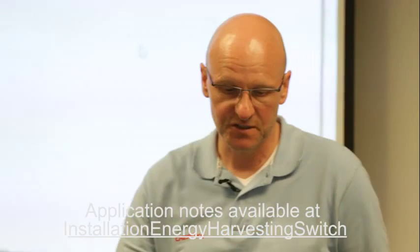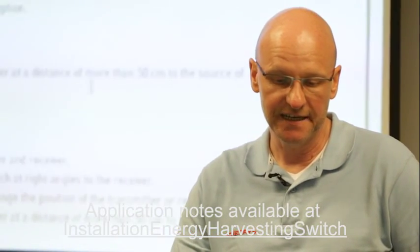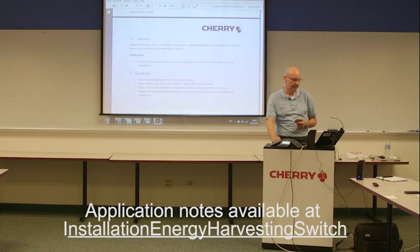Also reflections or interferences can happen inside buildings, as described in this installation guide. Jamming by other electronic devices could be another problem. So the application notes should give customers a short overview of what they should avoid or consider when installing RF systems. But you cannot cover all environments and all circumstances of a real application.